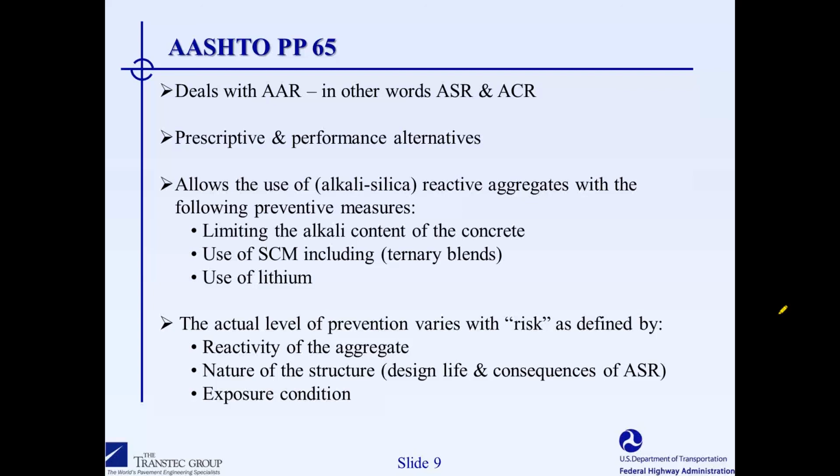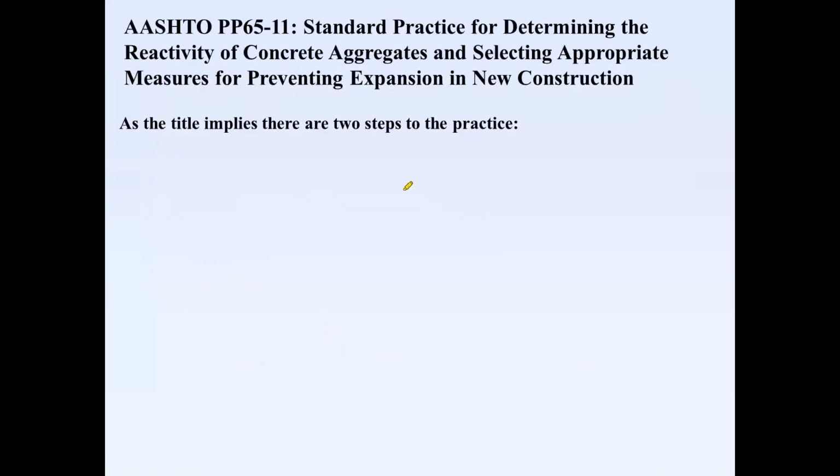And if you use the prescriptive approach in this document, the amount of prevention you'll end up with depends on the risk of ASR, as defined by the reactivity of the aggregate, the nature of the structure, and the exposure conditions. I should mention that the preventive measures in here only relate to alkali silica reactive aggregates. Alkali carbonate reactive aggregates cannot be used.